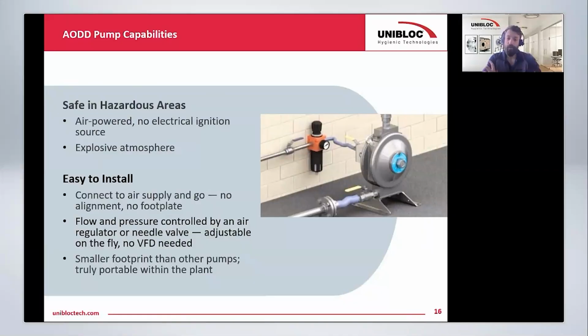And then they were maintaining the pumps in place, but often in these hazardous environments, you're going to take the pump out before you do the maintenance. And so having a pump that's easy to mount to a cart or easy to move is a great benefit of an AODD pump. And so for this producer, they ended up buying 6 of our diaphragm pumps and mounting them up like on a table, so at about waist height, so they could quickly and easily get in there and service the pumps in case anything were to fail.